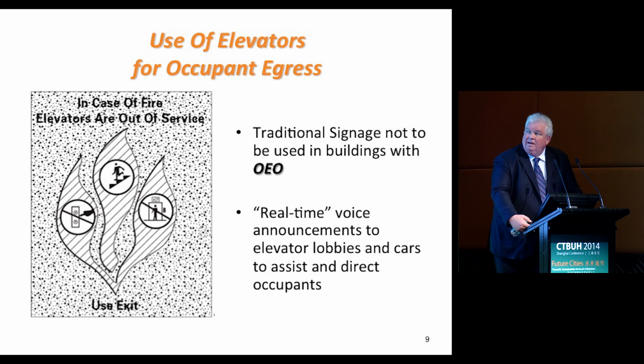Now, many of you may have seen this sign before. I noticed that something similar to this sign is on the floors here in this hotel, and it's been around for many years. And this is what people are used to seeing: don't use the elevators when there's an emergency. This kind of sign, of course, will not be used in a building that has occupant evacuation operation. We'll have what we call the real-time signage, and we'll also have accompanying real-time voice announcements for the lobbies and the cars.